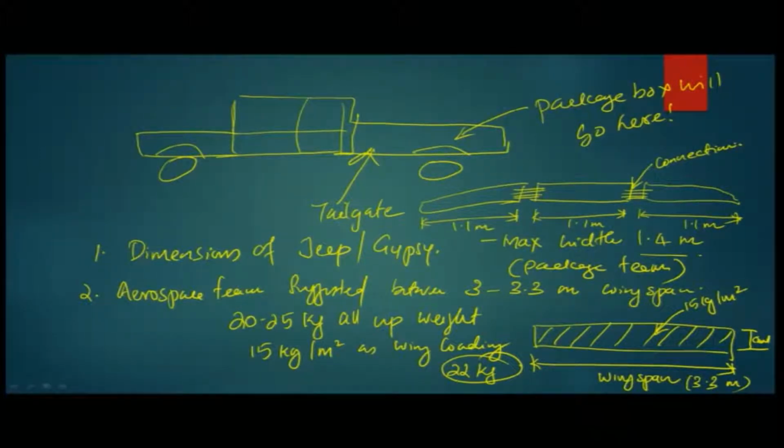Because the wings always will have their own control surfaces on them, your elevators, ailerons, all those kinds of things will be available on the wing. They are all controlled by servo motors, so the connections and the wiring have to run through that. So, it was decided that this is the central piece of the wing, and these two are the end pieces. The central piece of the wing was mounted onto the fuselage.